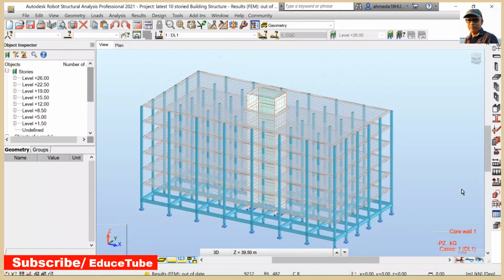Today my topic is the spectral analysis. Basically, the spectral analysis allows us to describe some phenomena, like variation of velocities, accelerations or displacement, depending on periods, pulsations or frequencies. And the main use of this spectral analysis in Robot is to describe the seismic action on a structure like this.